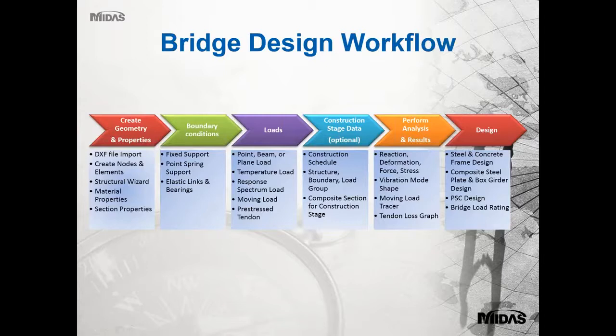Boundary conditions: after defining all your geometry and properties, we define boundaries, which can involve ideal fixed, pin or hinge supports, or soil springs, nonlinear bearings and releases, etc. Load conditions involve your dead loads, moving live loads, temperature loads, and settlement loads. We'll be looking at all these different types of loads in this basic training.